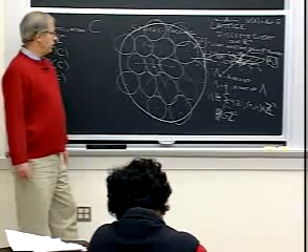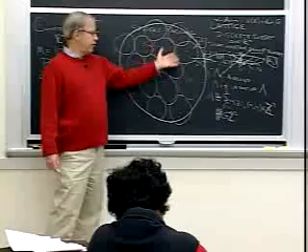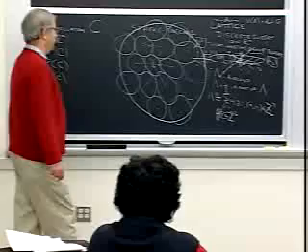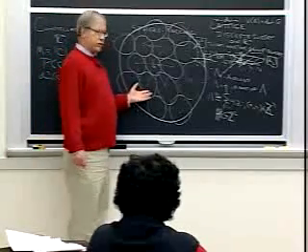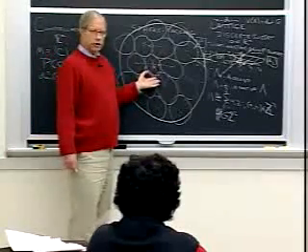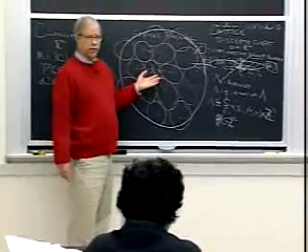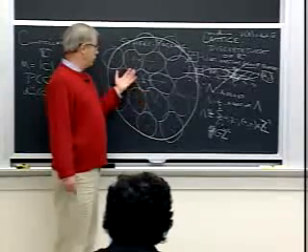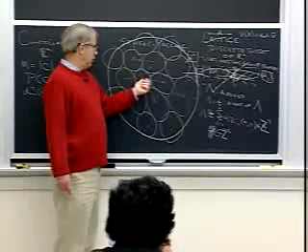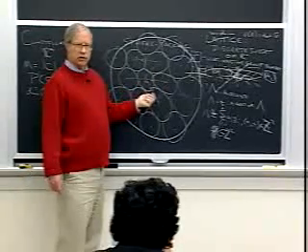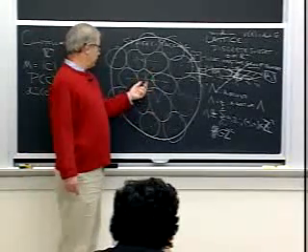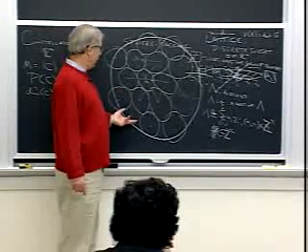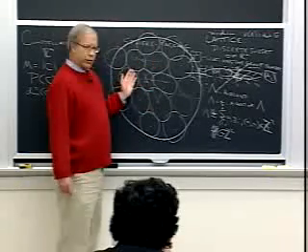One of the approximations I'm going to make: so what's the average power of that constellation? We could figure it out by taking 1/16 times the energy. I should say the average energy. I'm sorry, we're not talking power here. We're talking energy, but I read it as P. What's the average energy? It's 1/16 times the L2 norm of each of these points. If you like that, it's simply the Euclidean squared norm. All right, and we get some average.